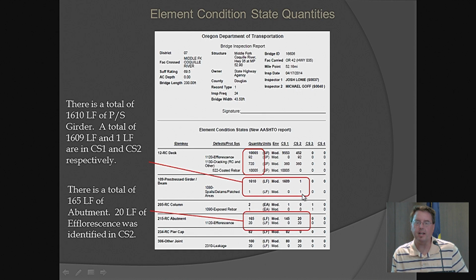again, when we go back to the example I showed where we had the coding guide, the little example for reinforcing, the defect language for the inspectors would say, like, for condition state 2, the spall is less than 6 inches in diameter. So he would say, okay, according to the breakout in the guide, say we have a 2-inch spall, that is less than 6 inches, so it's going to be a condition state 2.